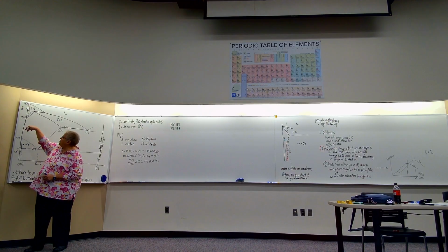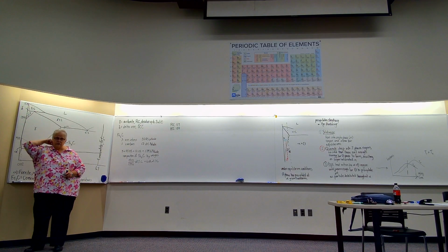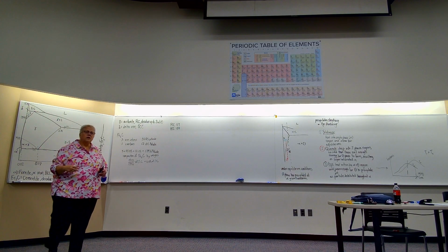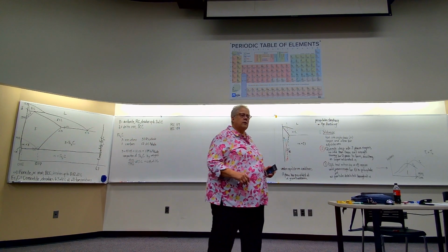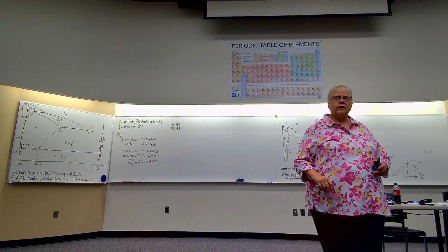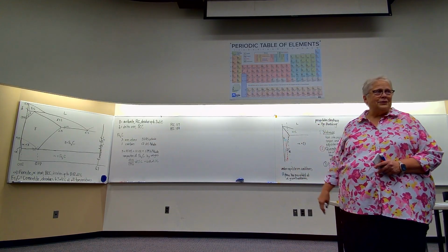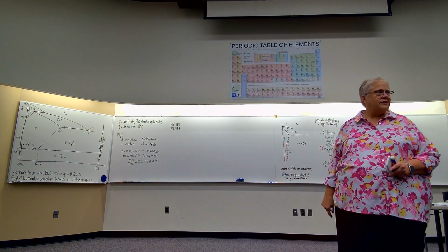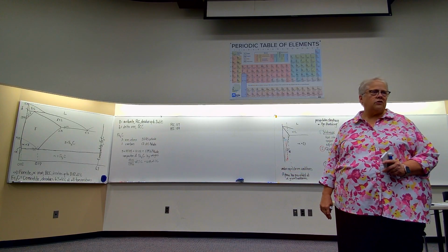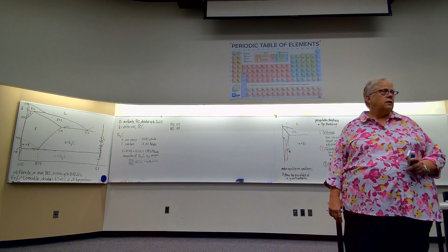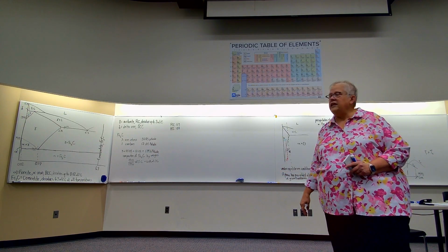Still, this is all solid, even at 1500 degrees Celsius. Still solid, cherry red solid. I think I can find you a phase diagram that has the temperatures, but then it also has the colors. Because back in early metallurgy, that's what they looked for, particular colors to know what phase you were in, in your heat treatment.